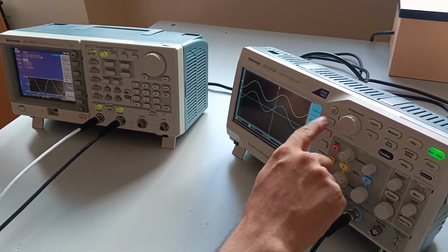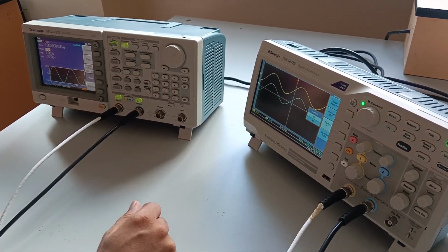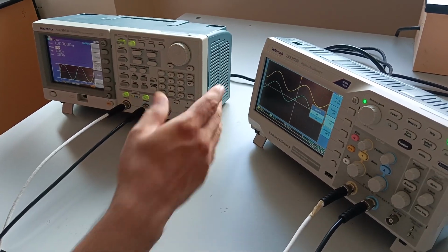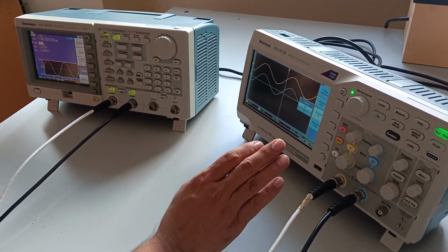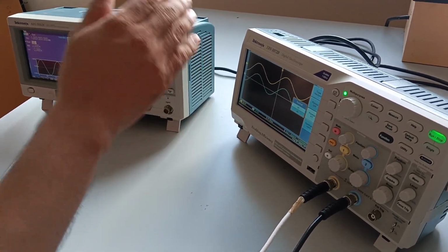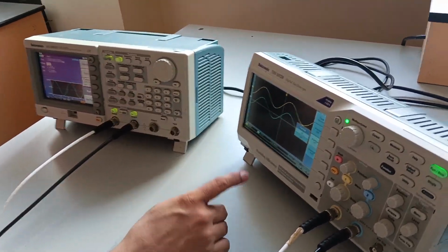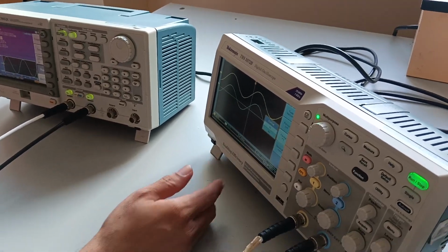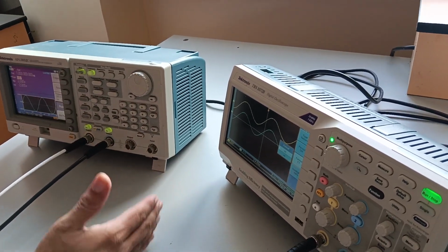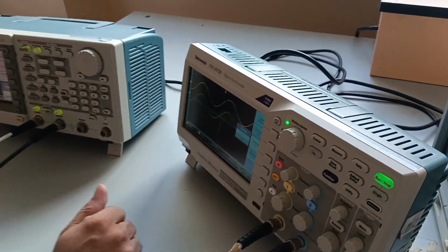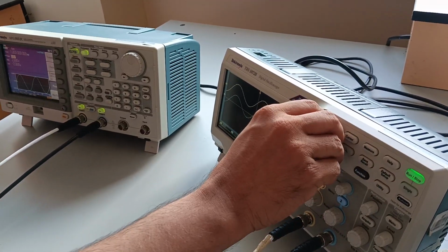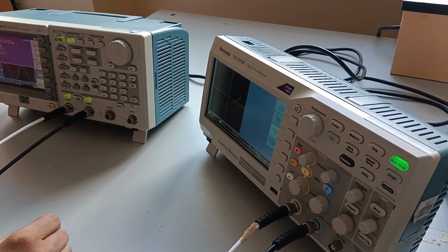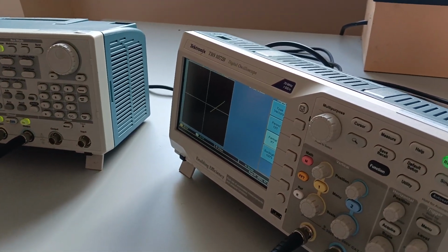utility display format. So what is this machine? You know, it's an oscilloscope. What does it do? It takes electrical signals and shows you the electrical variation as a function of time. So it is in YT mode, meaning Y as a function of time. It also has an XY mode in which this acts as the X-axis, this acts as the Y-axis. So if I go to XY mode, it will look like this because both are sine waves.